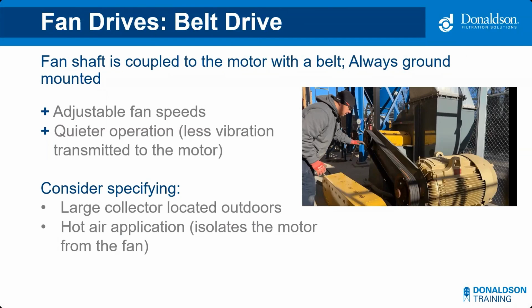Another example of where we might want to use a belt drive is when the temperature of the airstream is too much for a direct coupled motor. So we remove the motor, get the motor away from the airstream, and use a belt drive to drive the fan.